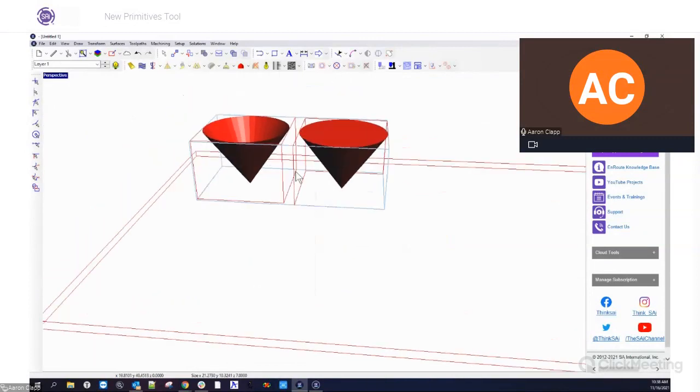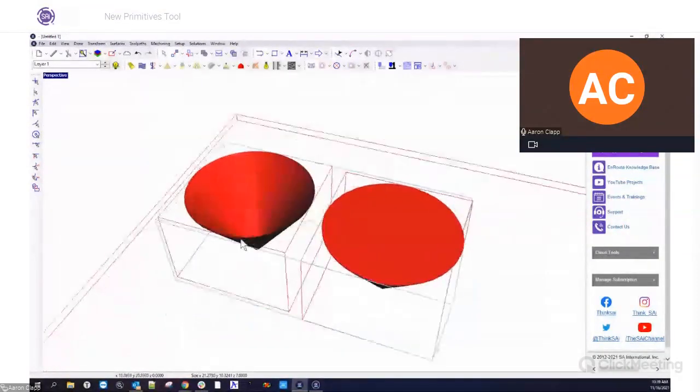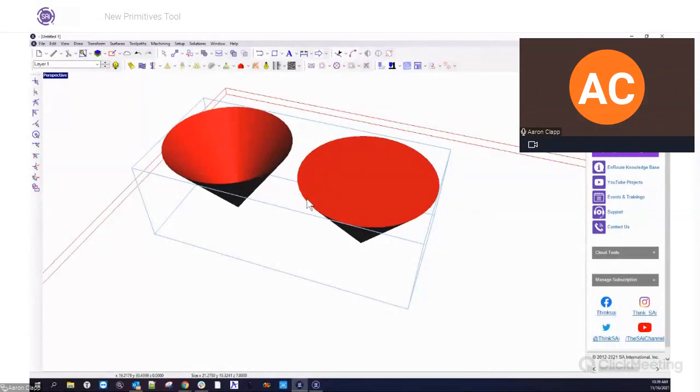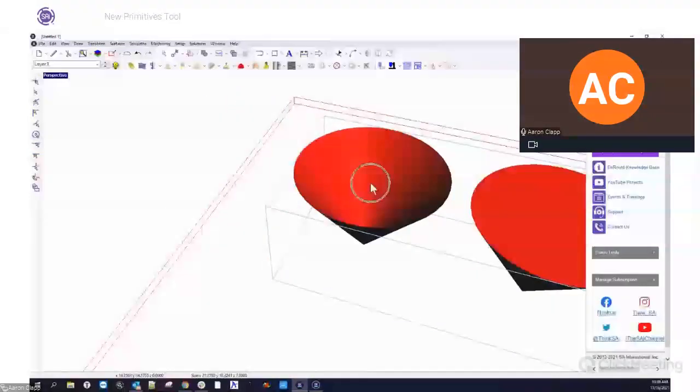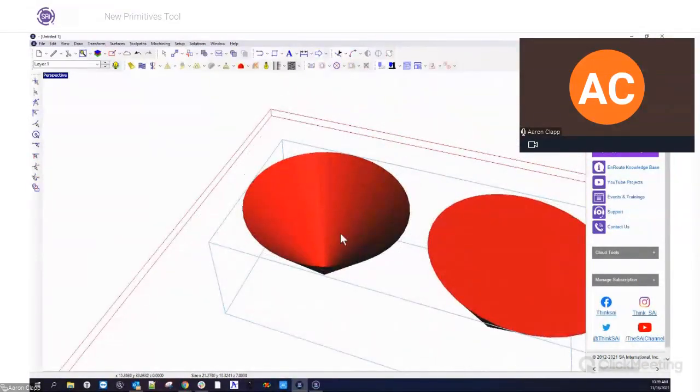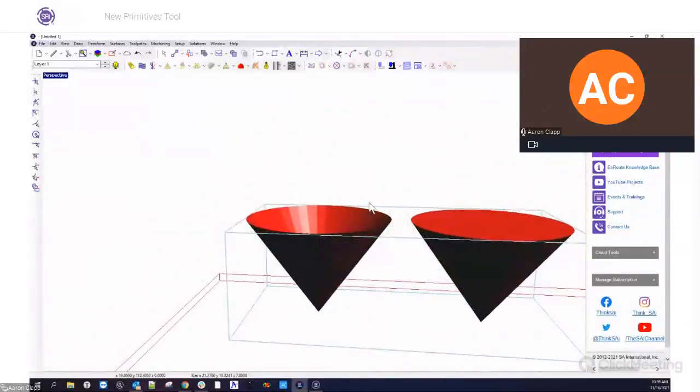Now, the nice thing here is that if I open the bottom on some of these shapes, I can now create a reverse of the shape. So now I could carve this into material, whereas the closed bottom just creates a nice seal on here so that if this needed to be flat, then that would help with your relief creation as well. But either way, we can create a relief on both of these objects, and this one would just get created in the negative space, carving down into the shape.